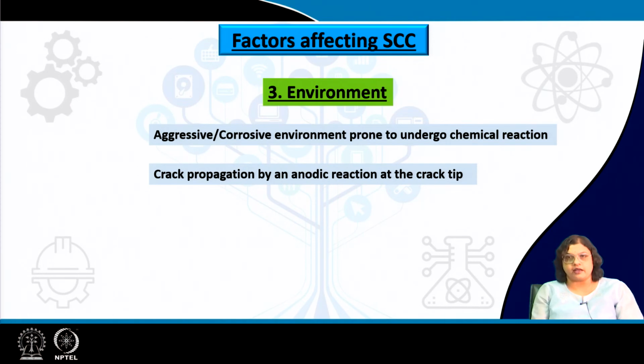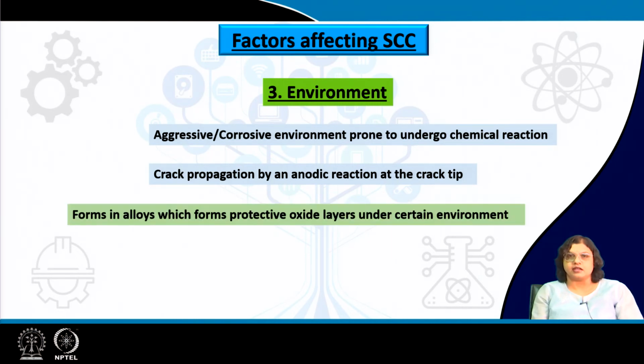as we have already seen how the entire component behaves as an electrolytic cell, with the anode at the crack tip and the cathode at the wake of the crack, which is surrounded by the passive zone, as well as the corrosive media as the electrolyte. This entire reaction will keep on occurring in the presence of the environment and in the presence of this tensile stress as well.